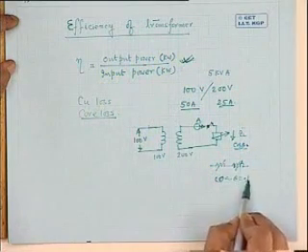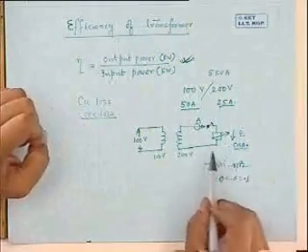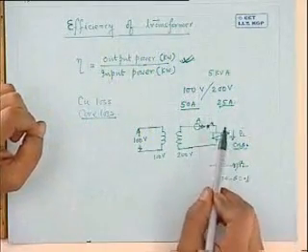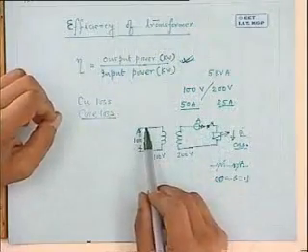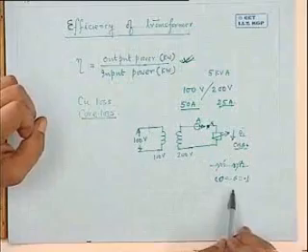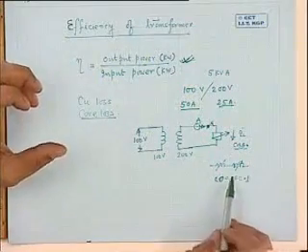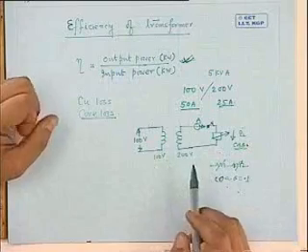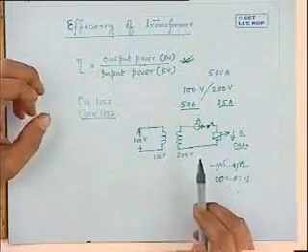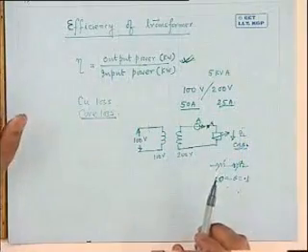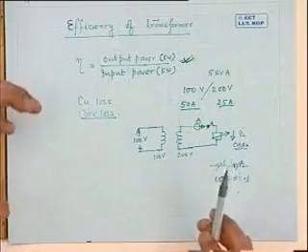Now cos theta could be anything. Suppose I decide cos theta is set to a very low value, 0.1, and I manipulate Z2 such that 25 ampere flows this side and 50 ampere this side. Similarly, for another power factor, say 0.8, I can also realize the same current conditions of the secondary and primary. Are you getting it? In both cases, the transformer is fully loaded, no matter whether it is delivering rated kilowatt output to the load or not.